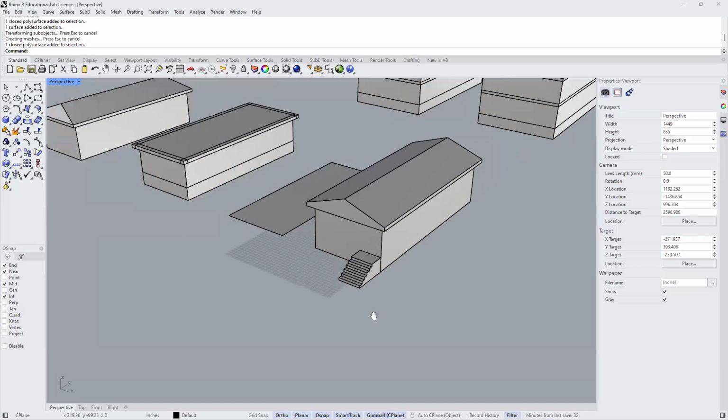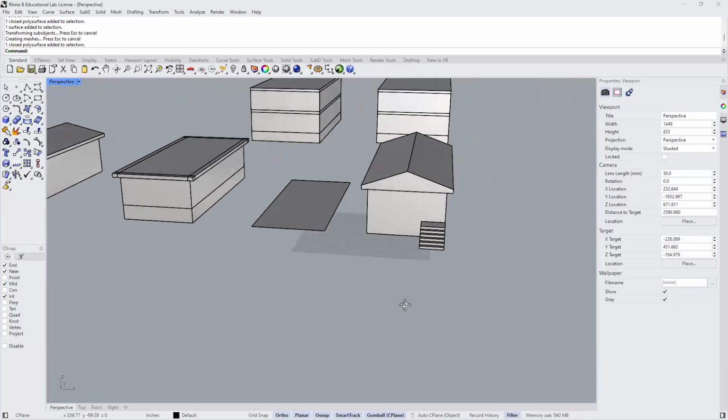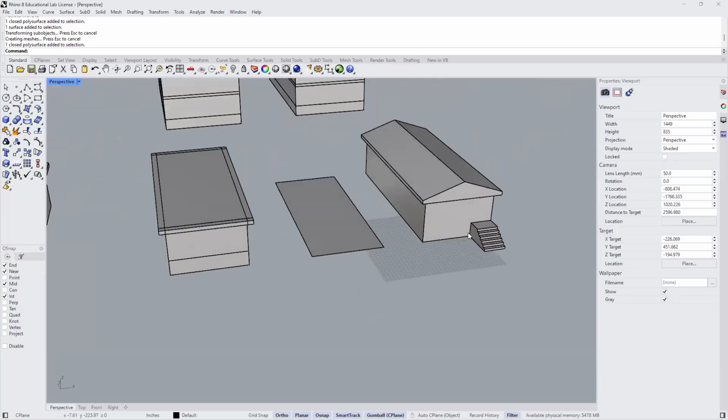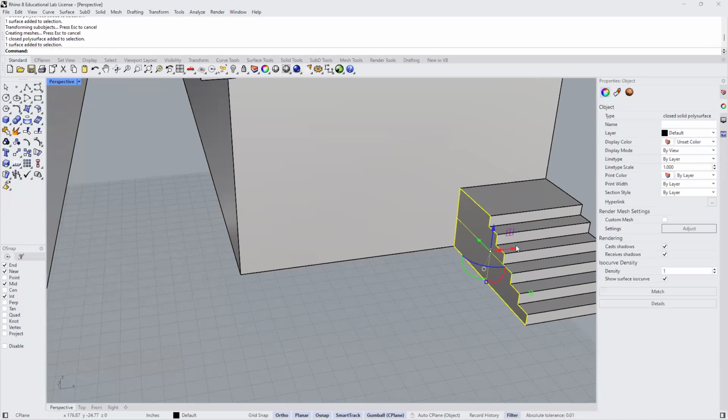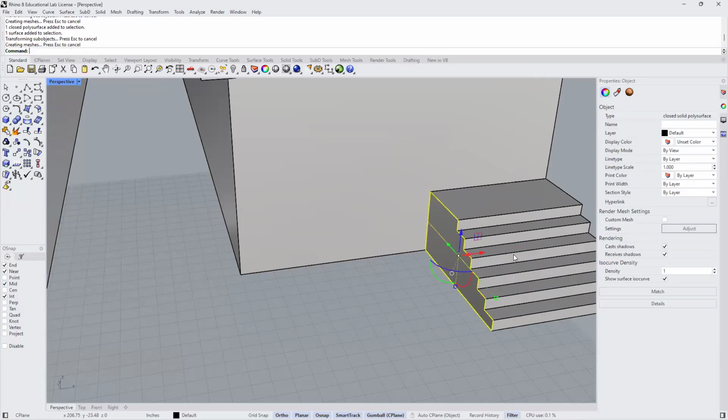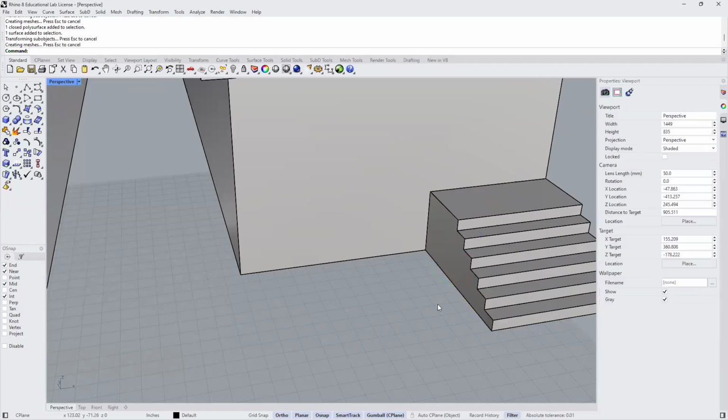And I'm just really showing that this is the house I'm going to walk up to, and maybe I want to make the steps a little bit wider. So I'll hold down Control Shift, click on that surface, and click on the red arrow. And I want 2 more feet, so it's going to be -2 feet, just because I'm looking at the arrow, and I know it has to go in the opposite direction. And I'll click off of it, and that's it.